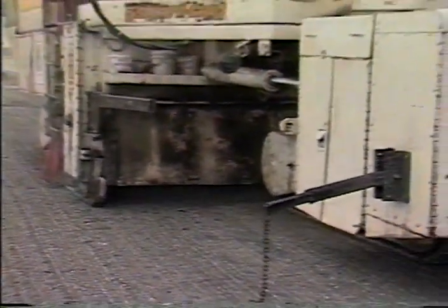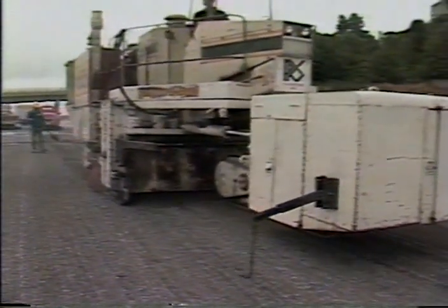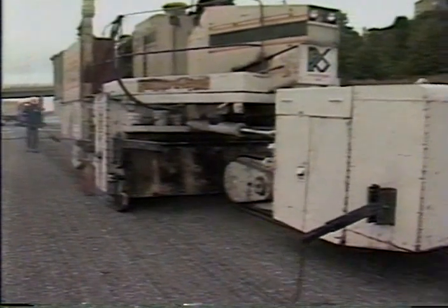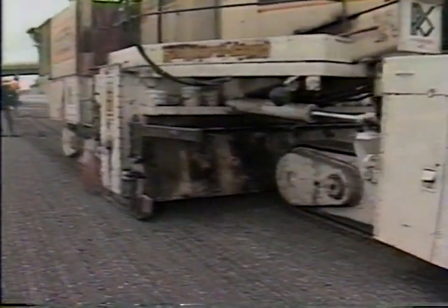Although shot blasting leaves the surface ready for overlaying, secondary cleaning is recommended just ahead of the overlay placement. Cold milling is used when deep removal is required. This procedure can remove up to 1 inch of the old concrete, leaving a very rough surface that helps bonding. In some cases, though, milling may cause some micro-cracking at the surface and spalling at the joints. A secondary cleaning is required when cold milling is used.